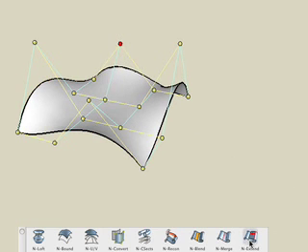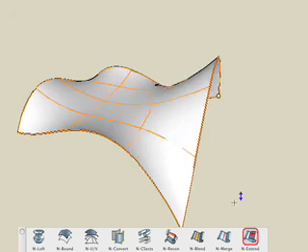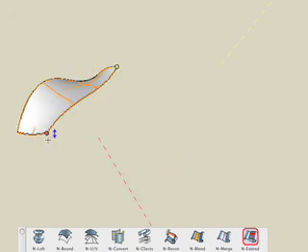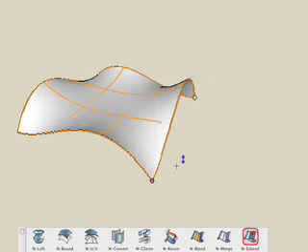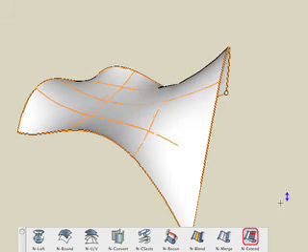Select the Nurbs Extend tool and click on an edge of the Nurbs surface. Control points will appear on the selected edge. Simply click and drag the control to retract or extend the edge along the curvature of the surface. Notice that the controls are maintained along visible guidelines, which maintain the curvature of the existing surface.